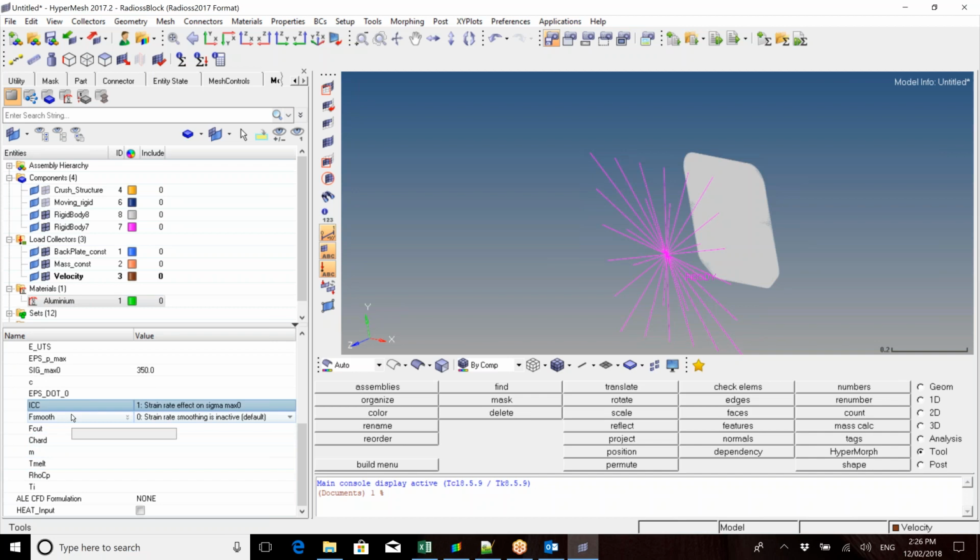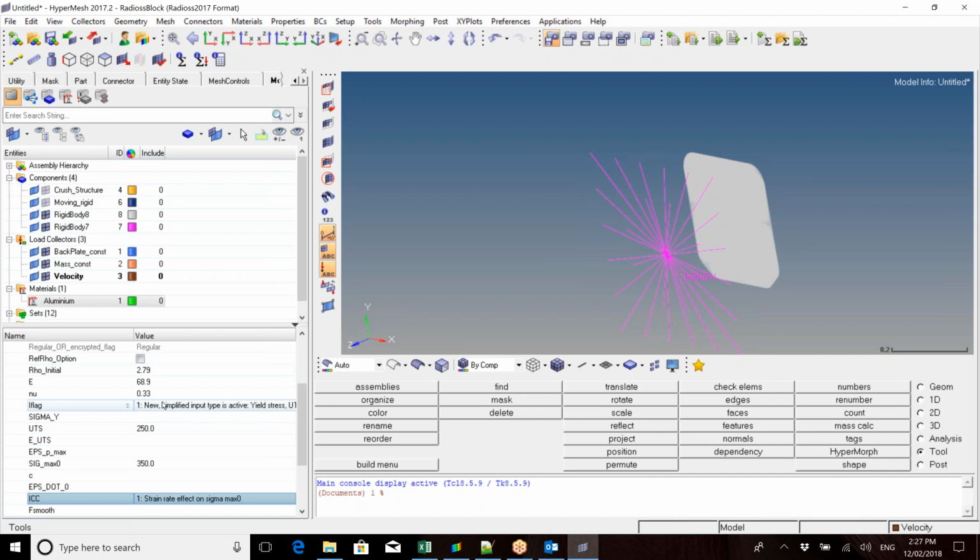So we've got, and then you can look at your flag rate for smoothing. You've got your cutoff frequency for smoothing. So you can see there is actually a lot of stuff to go through when building a nonlinear model. It's not as straightforward as a linear. And then there's full temperature components as well, but I don't think anyone here should be working in melting temperatures, especially not for the crash structure. So you should be fine to leave that. But we'll just put that in for the moment, just so you guys get an idea of it. And then